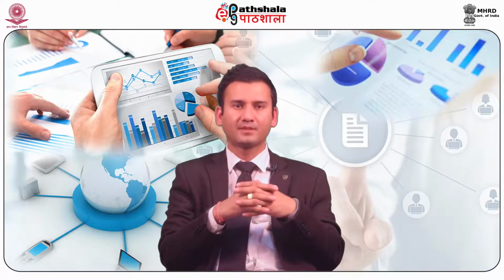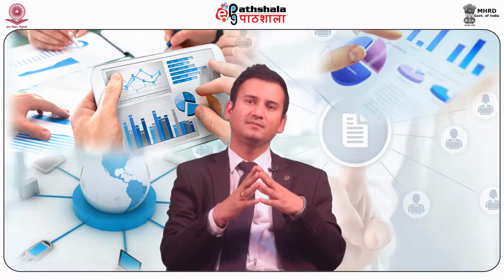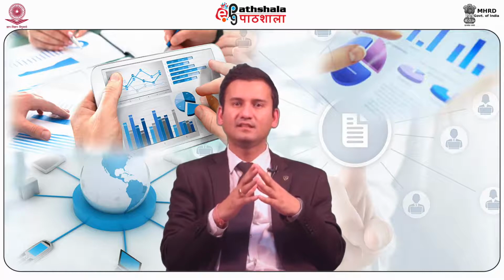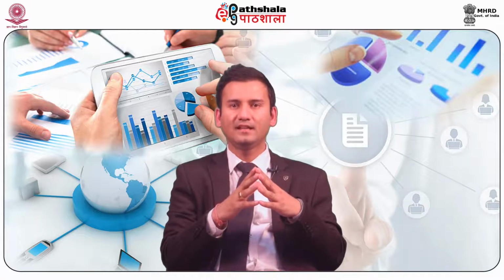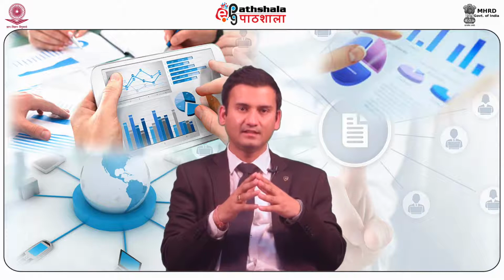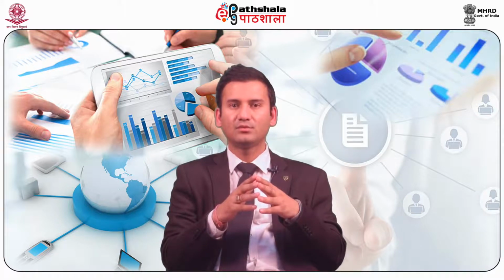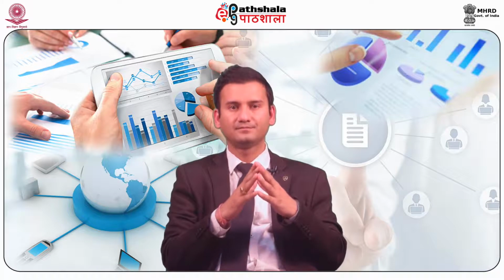Batch flow process. A batch process is similar to a job shop, except that the sequence of activities tends to be in a line and is less flexible. In a batch process, dominant flows can be identified. The activities, while in line, are disconnected from one product to another. It means a batch process executes different production runs for different products.